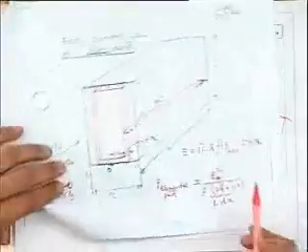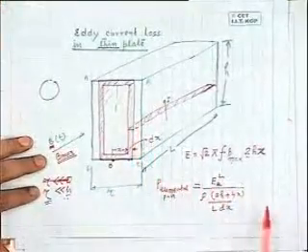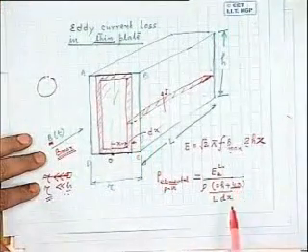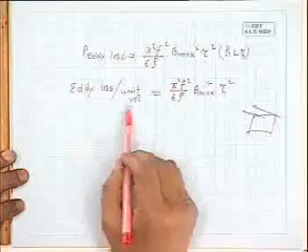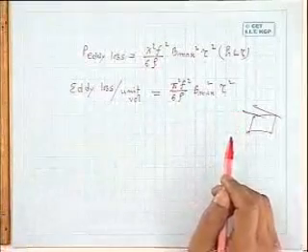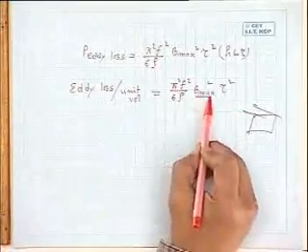If you apply it, you are gone, because it depends upon this crucial approximation that thickness is so small, I can neglect this 4x compared to this 2h. That is there, because I know I have to make the plates thinner. In fact, transformer plates are used of thickness 0.35 millimeter or so. This I will tell you in great detail after, when I take up construction of the transformer.